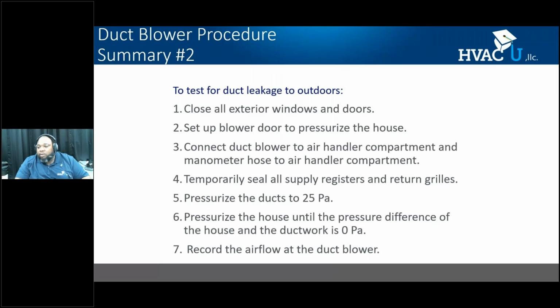We're going to connect the duct blower, like we've seen in our previous slide, to the air handler compartment, just like we would do a typical duct leakage test. We're going to temporarily seal all the supply registers and return grills, like we talked about. We're going to pressurize the duct system to 25 pascals, so that hasn't changed. But now we're going to pressurize the house until the pressure difference of the house and ductwork is at 0.